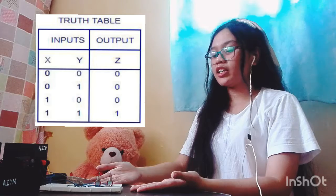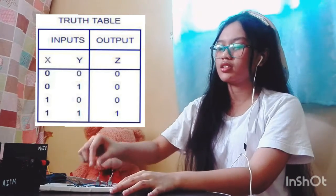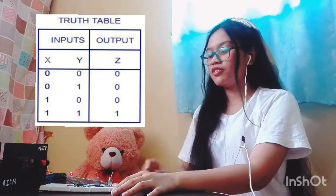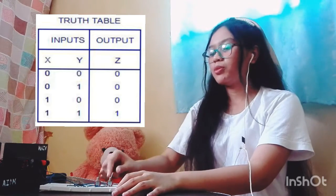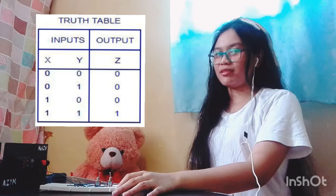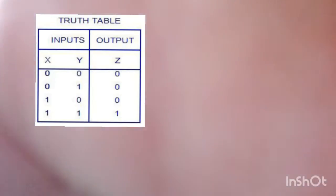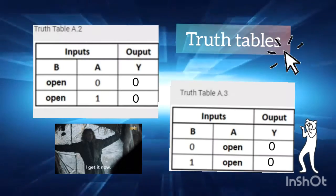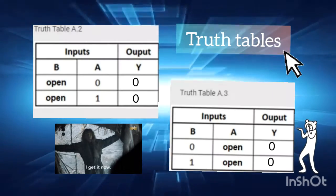Now, let us test our circuit number 1. Let us turn our power supply on for the 5 volts VCC. Here we have an AND gate circuit. The LED will only turn on if both of the switches are in high input. The LED will turn off if any of the switches or both of the switches are in low input. And here are the other truth tables with open input in a combination.